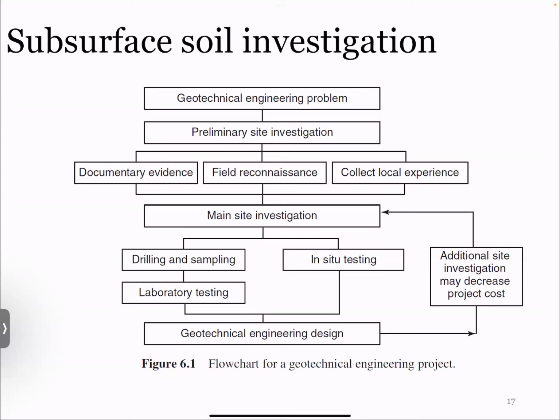And oftentimes what we do is an iterative technique. We first have our first round of initial subsurface investigation and drilling. Then if we see an area that is a little sketchy or problematic, we go back and do a phase 2 study to hone in on that one specific condition. This helps the project be a little more streamlined.